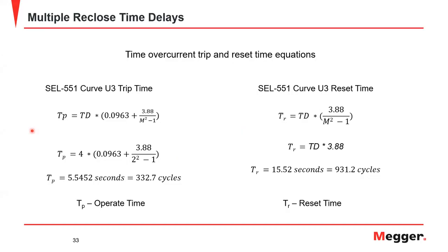Thank you. Our next question is going to be for Abel. If we have an electromechanical relay as a backup and a microprocessor relay as a recloser, what recommendation do you have on coordination, time lag, etc.? Another interesting question, and the answer to this one is do a proper short circuit study, and the tool that you're using can tell you what are the proper coordination times that you have to use for both.